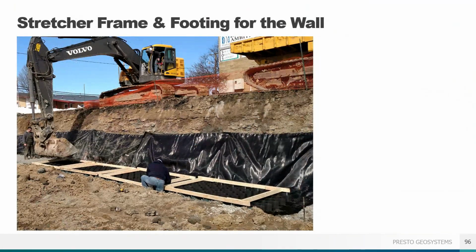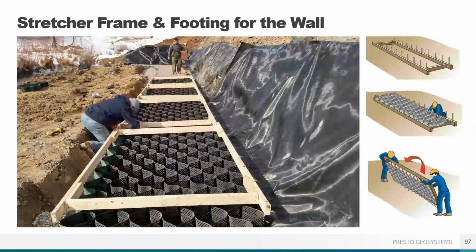And here are the stretcher frames from another angle. The stretcher frames are placed spikes up, and then the GeoWeb is placed over the stretcher bar. Once the section is open to optimal size on the frame, the frame and GeoWeb are flipped over, making sure the fascia panel faces the proper way, towards the front.